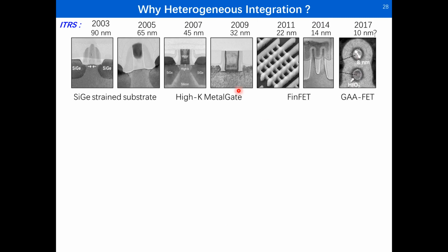The main part of ITRS is CMOS shrinking, or the front-end process. Everything must get adapted to it. However, this road is hard to go, as we know that after the 14 and 10 nanometer technology, it is very expensive and very difficult to shrink further.